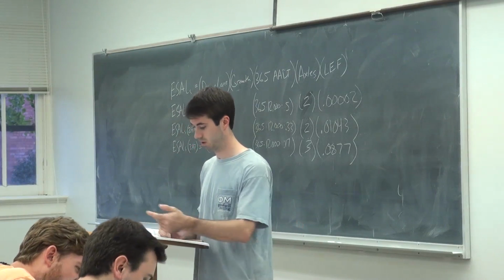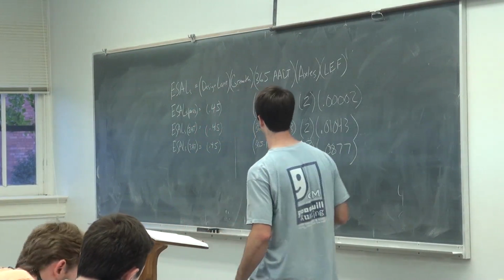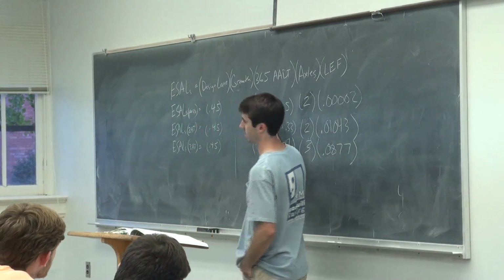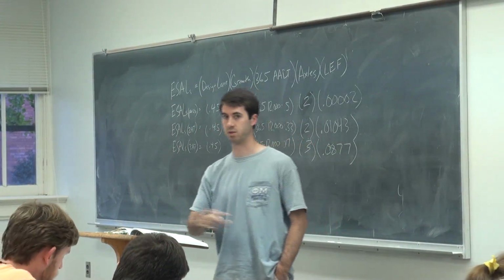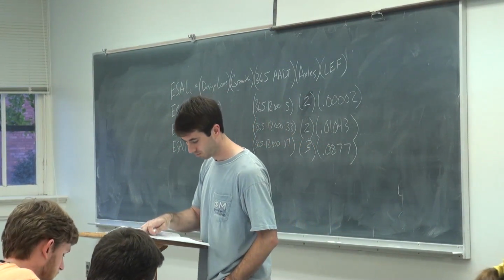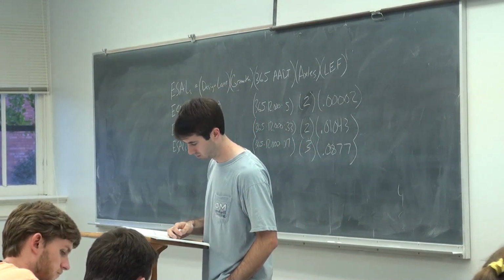We're basically in the F given A case, where we're assuming traffic is going to be 12,000 year after year, but it's going to grow some. But we're putting 12,000 on it every year. So what would be our growth factor?